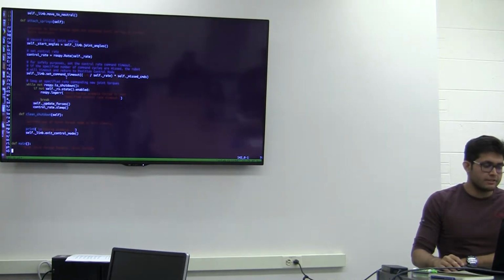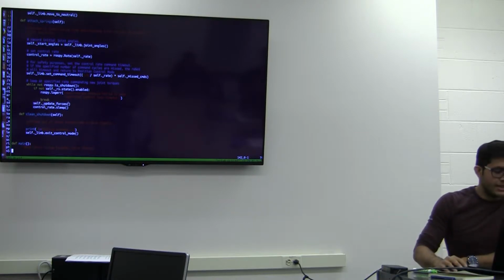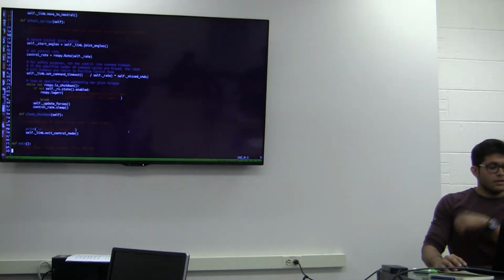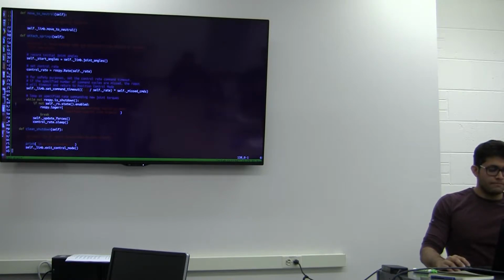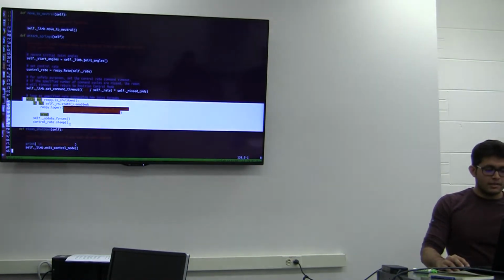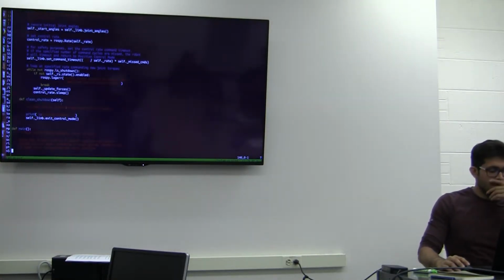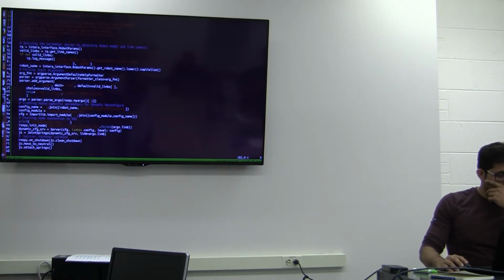Attach springs, now it's like creating the instance or giving out the values and stuff. Update, this is the loop where every ROS command is running. You can see this loop, right? This part here. So it updates the forces, it calls this function basically, and it moves the robot there. Dynamic servers move the joints there. So that's where the execution is going on, like new data is given to the ROS command, like ROS publishes it kind of thing. And what else?